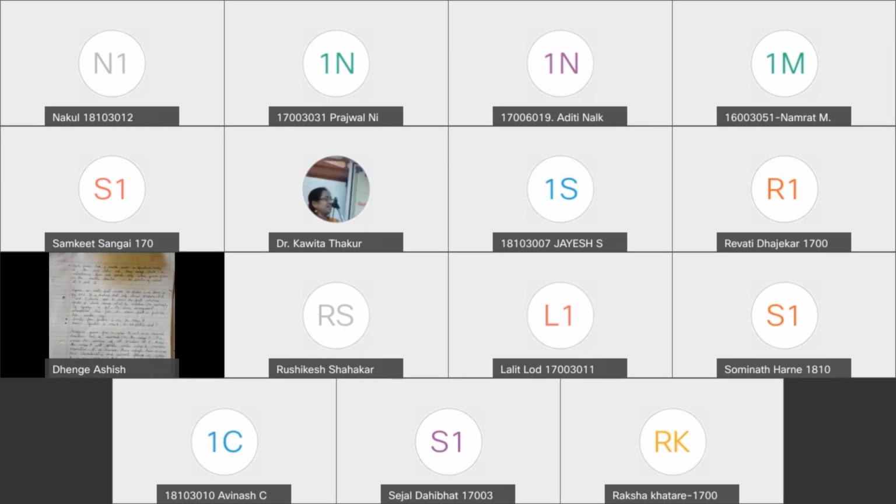Suppose an earth fault occurs on feeder 1. Then only one circuit breaker will operate to open and clear the fault, whereas at feeder 2 the circuit breaker will remain closed for continuity of supply. In fact, the above arrangement accomplishes this job. Therefore, in parallel feeder, the power flow will be in the normal direction, but it is reverse in the directional relay, which is at the other end. In this way, we can